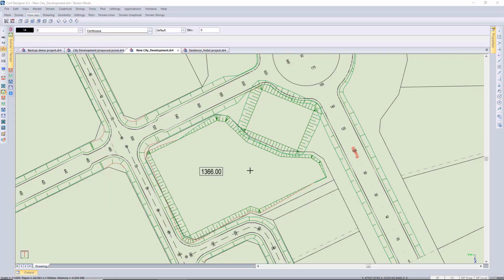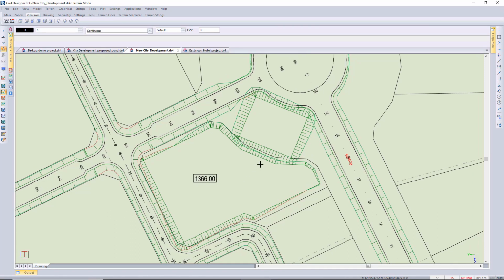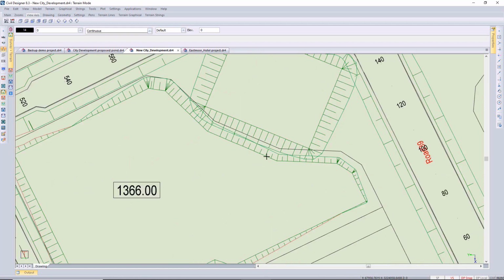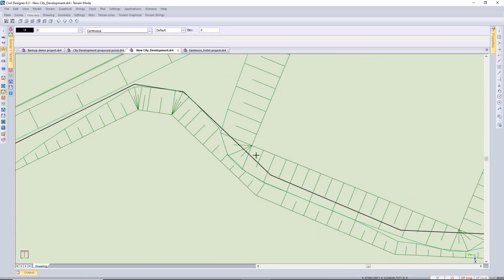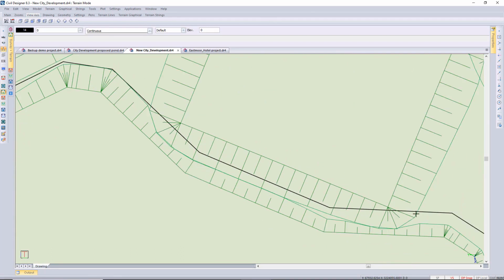Hi there. In the previous Survey and Terrain webinar, we had a look at the strings platform design, and we had these two overlapping platforms. I had a question on how to tidy up these overlapping banks, and there's a function under the strings pull-down menu, recalculate all, which is designed for this purpose. Running that function, it'll look for overlapping areas in your banks and then tidy up and neaten those banks. You can clearly see there that those two bank lines are now neatly trimmed.